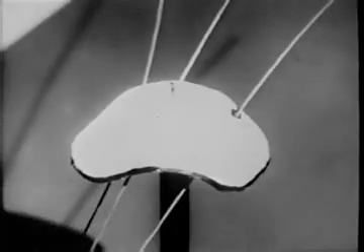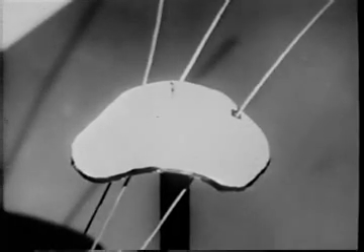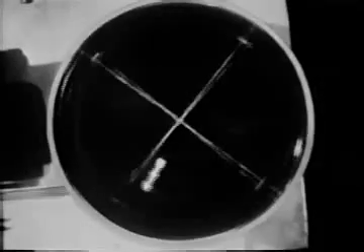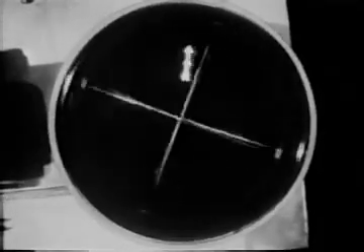So if there is a definite circulation around some curve, then the enclosed fluid must have vorticity. But if the circulation is zero for every curve in a certain region, then the fluid in that region must be entirely free of vorticity. Sometimes the vorticity is everywhere in the fluid, distributed throughout. But often the vorticity is very large in a thin thread of fluid, while the remaining fluid is without vorticity.